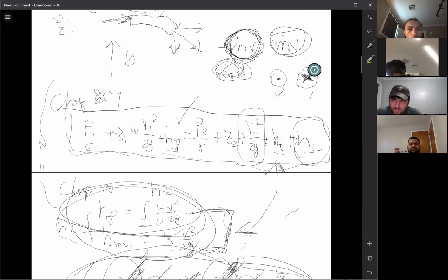Basically, it's easy. So basically, you look at this. If you have two unknowns, I will circle the two unknowns in this equation. So you use conservation of mass to find this unknown. So if you know how to do conservation of mass problems, just like what you practiced in chapter 5, then you should be able to find this velocity using conservation of mass. Then substitute into that one. That's probably the easiest one to tie conservation of mass and Bernoulli and all that together.